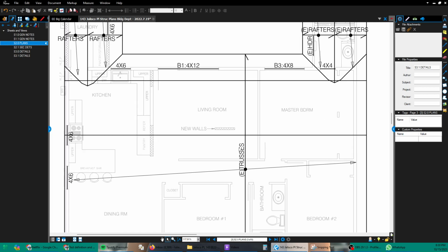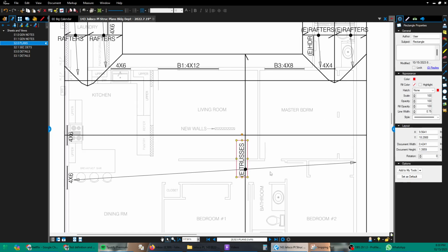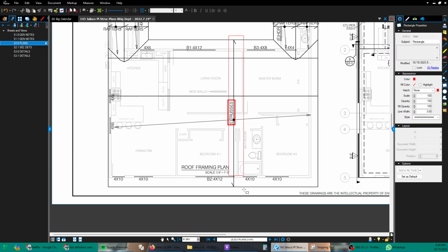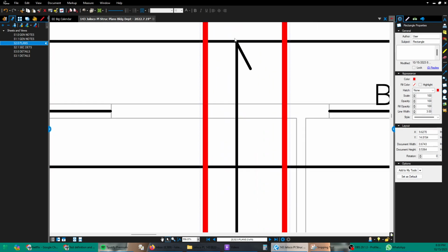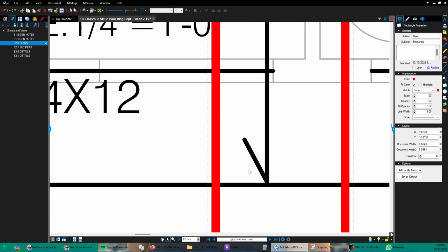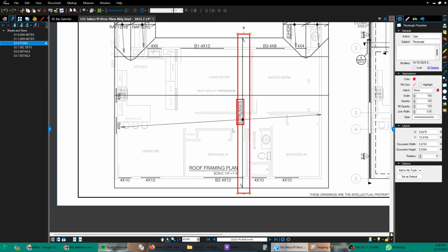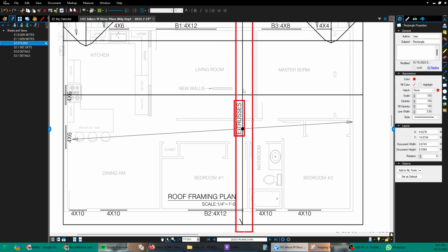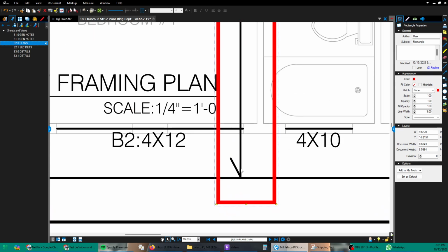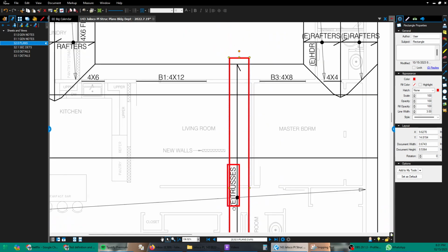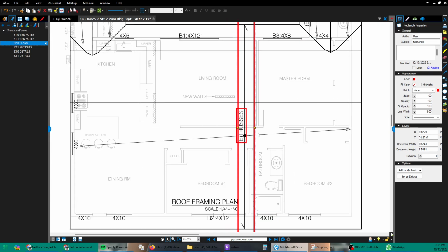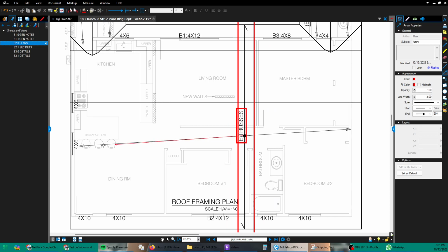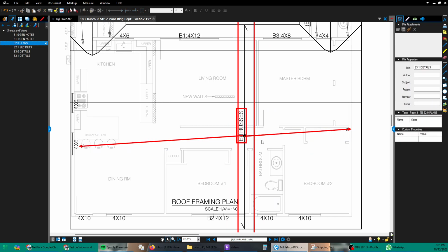So this indicates what? This is the trusses, existing trusses. This indicates their extent, right? Where do they start? Where do they stop? They go from here to here, right? Those are the trusses, and then that's a single truss, right? This is saying each truss goes this far. And then the extent arrows here are telling you over what range of the building is that true, okay?